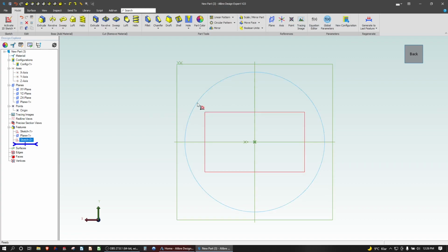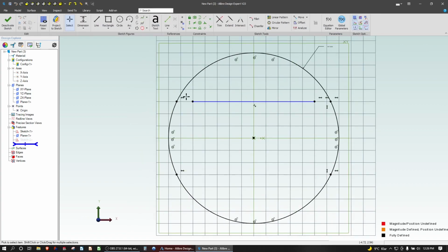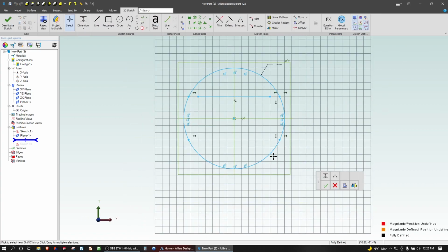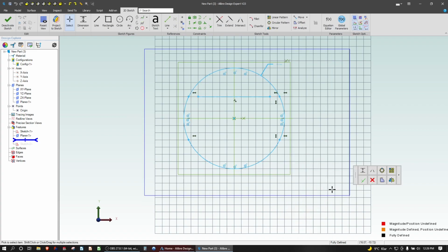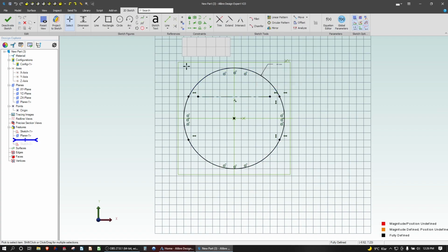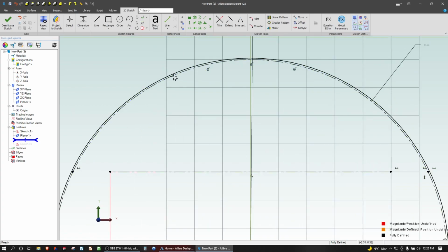So why don't I open my sketch? I'm going to select everything, and we're going to say convert. I guess I have to select everything and deselect my reference figure. We'll right click, convert to reference figures, right? So this will be not driving the loft anymore. Let's go with a circle, and I'm going to make it just a slightly different size, and that way it's easy to visually differentiate what we've made. How about 14.1, right? Now we can see both a little bit easier.